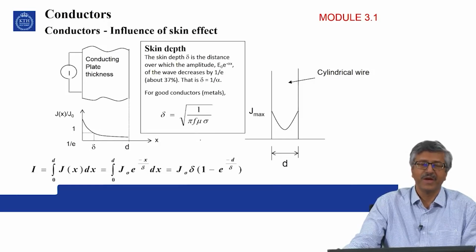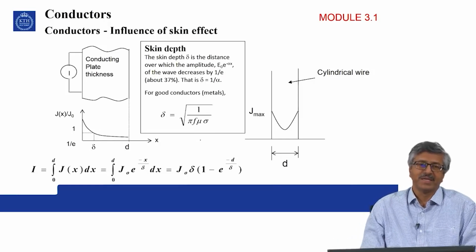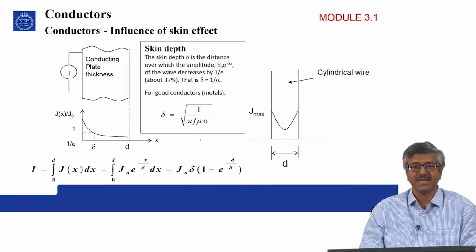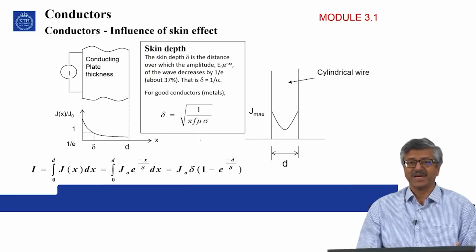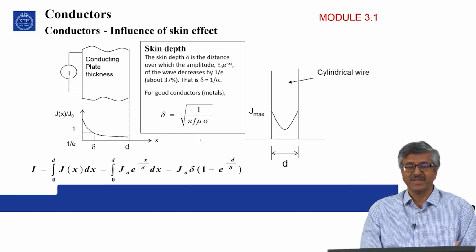So, for example, if you have a superconductor, since you cannot have any field penetration inside the conductor, all the currents will be confined to the surface because it is superconducting, conductivity is infinite theoretically. So, you cannot have any electric and magnetic fields inside the conductor. So, there cannot be any current inside or potential difference inside.